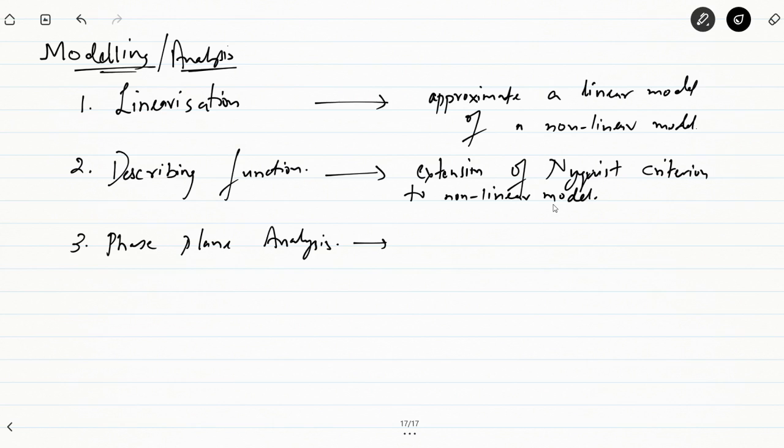The ratio of the fundamental component of the output to the input component will be just like a transfer function, making sure we are able to get the amplitude and the phase of the system from that describing function. In other terms, just as in a transfer function we obtained Y(s) by R(s), here we'll obtain the fundamental component of the output at frequency omega divided by the input component. The input will be a sinusoidal input, and we'll see what the fundamental output of this particular system is. From this ratio we'll obtain the magnitude and phase, as we did in polar plots and Nyquist plots.